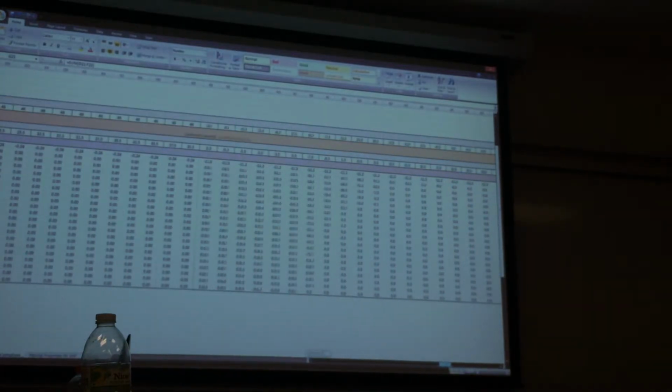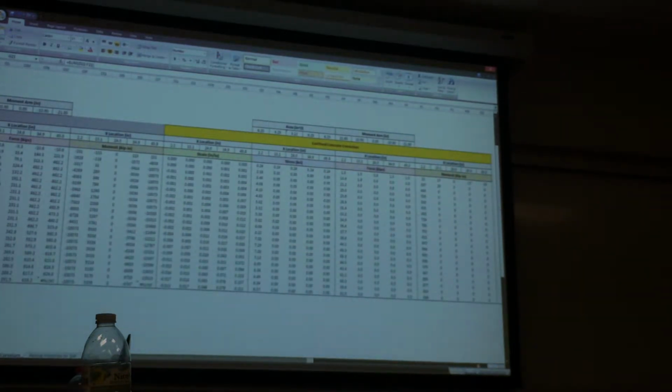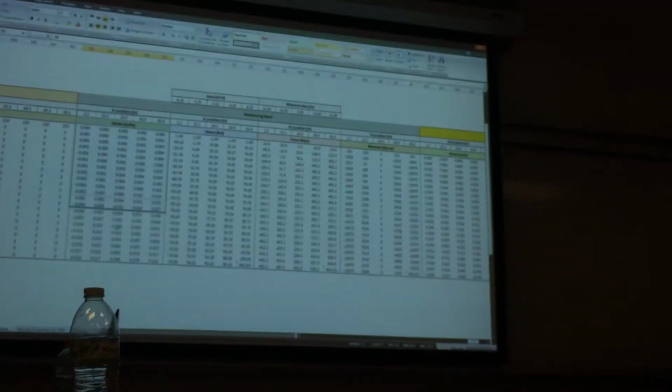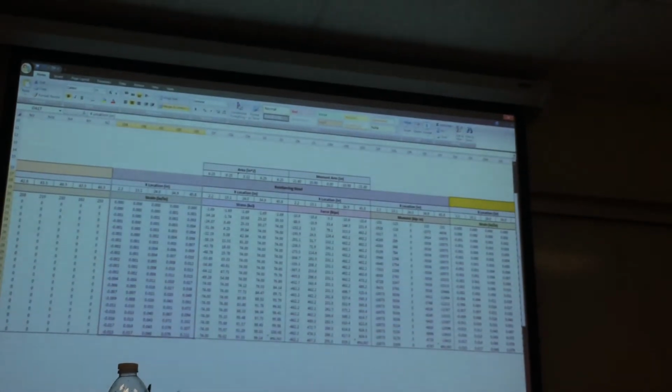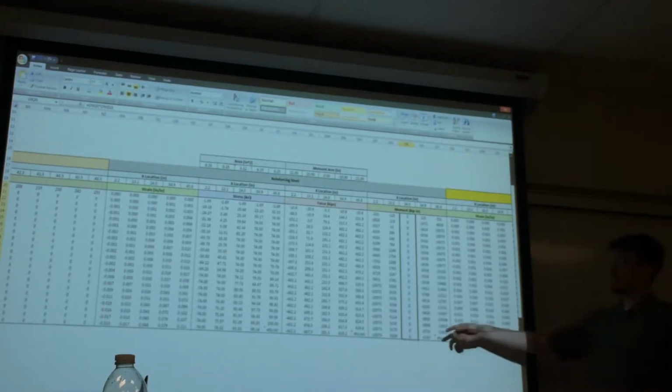The one correction I sent out on the announcement was, going through this last Wednesday with you guys, I mentioned there were 4 fibers. At the time, that didn't look right to me, and of course, I missed finding that central fiber. But you should have 5 steel fibers. You have 5 bars. What I was trying to say, and probably did so poorly, was that this central fiber here, at the very middle of the section, if you look at the moment contribution of this set of steel fibers, it's always 0, because your moment arm to the center of your section is going to be 0. So those bars don't contribute at all to the moment capacity of the section.